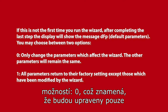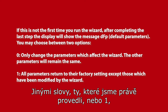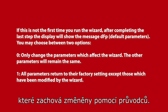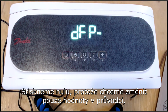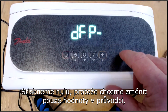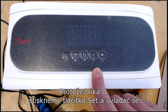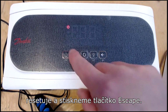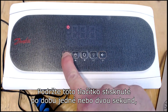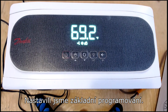0, where only the parameters included in the wizard will be modified, in other words, the ones that we just did, or 1, where parameters modified by the wizard will be changed, and all other parameters will return to their factory setting. We will press 0 as we only want the values in the wizard that we modified to be changed. So since it's flashing 0, hit set, and the controller will reset itself, and we hit escape, hold that button down for a second or two until the controller goes back into control mode. And we are done. We have set basic programming.